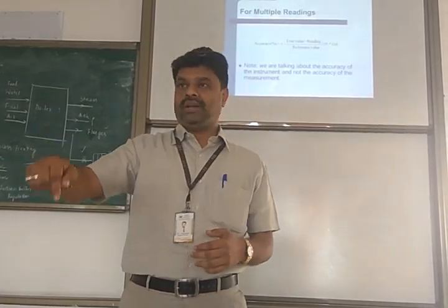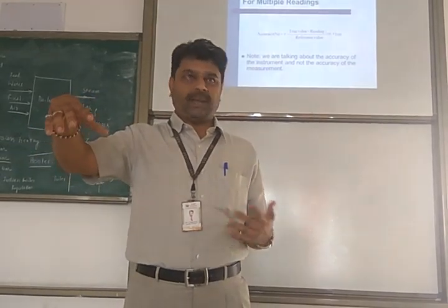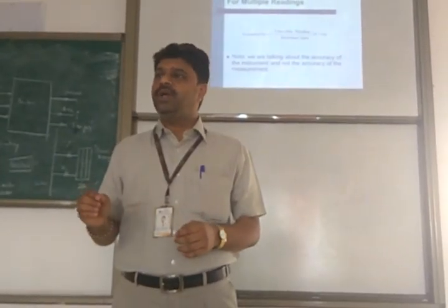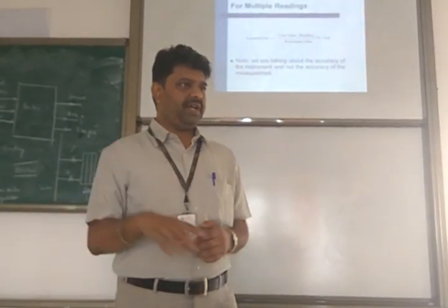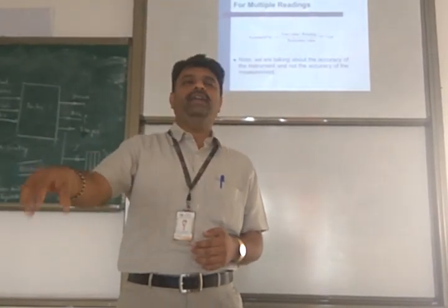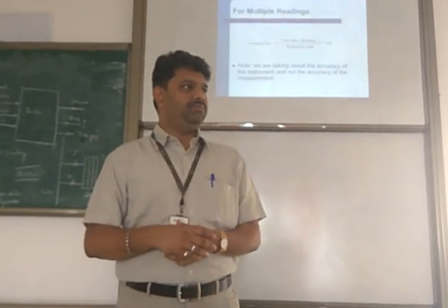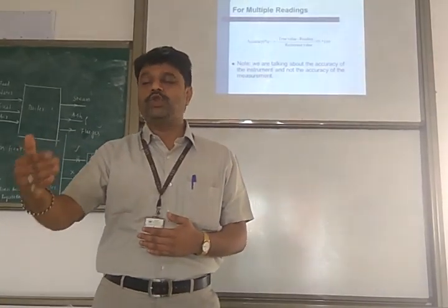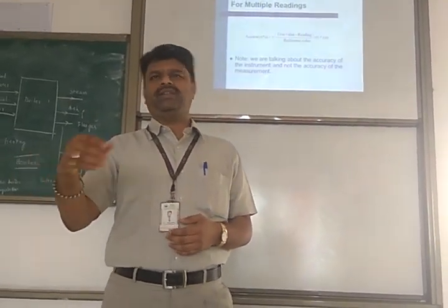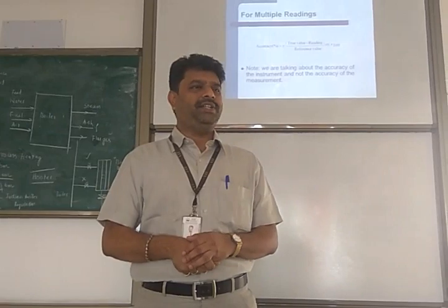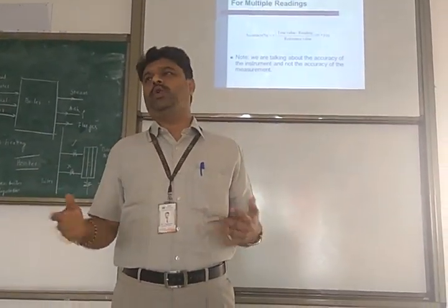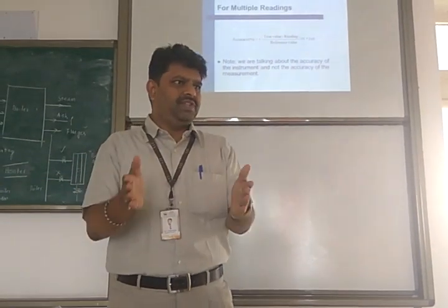I will have one more reference temperature measuring instrument, maybe some other type, which I call a reference meter, which will give you 3 digits of information. So that's the reference value, and I measure the reference value. Reference value, that means true value. Let us say now it is 70.33 something. Okay, 70.33 is the true value. When I put my instrument, it will show 71.2 degrees Celsius, somewhat far away from the so-called true value.